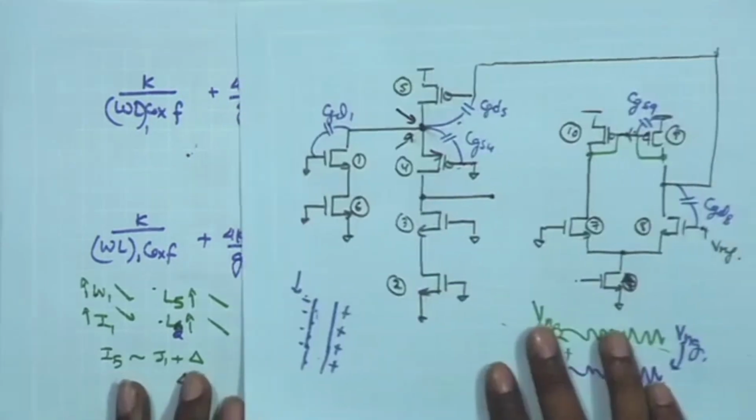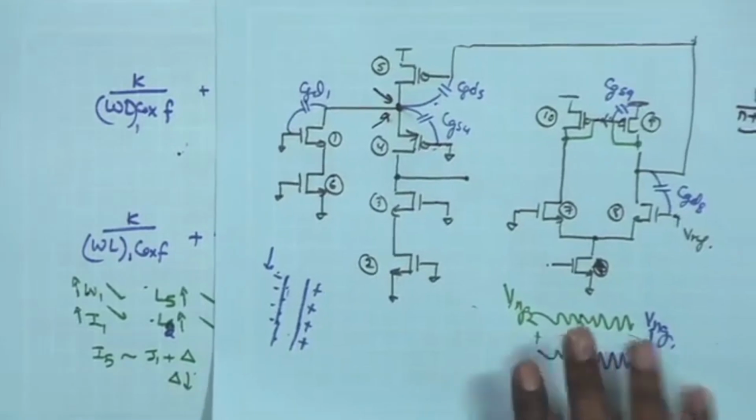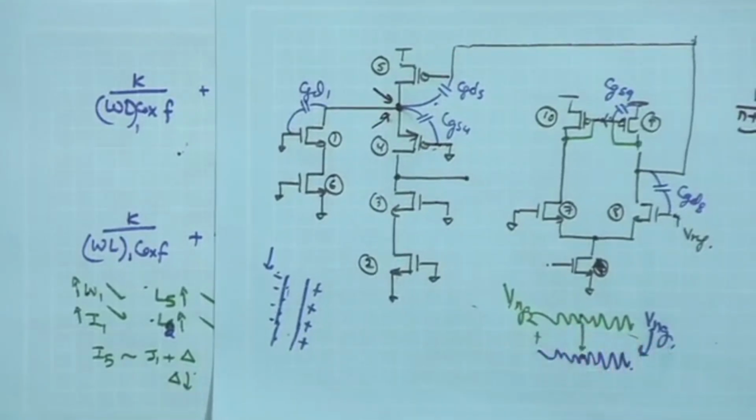So, as the next step, now that we have done this analysis for noise, frequency response, swing, etc., we will take a couple of examples where the design steps will be shown algorithmically: given the design specs at the higher level, how do you come back to the transistor level design, and how do you approach the sizing of these different transistors step by step in a logical fashion, considering all these constraints and design requirements in terms of specifications.